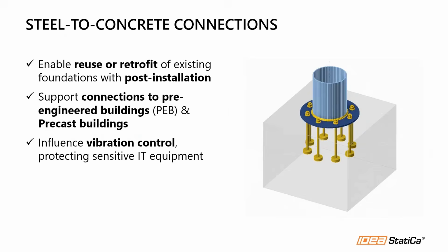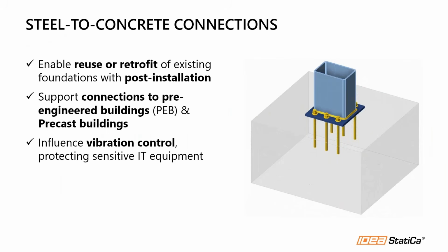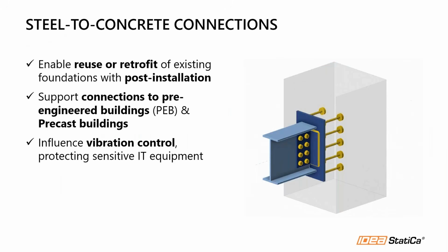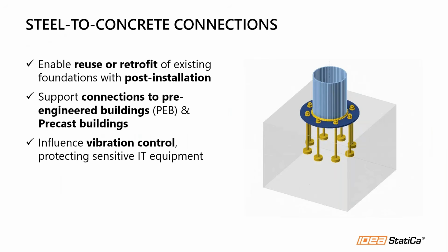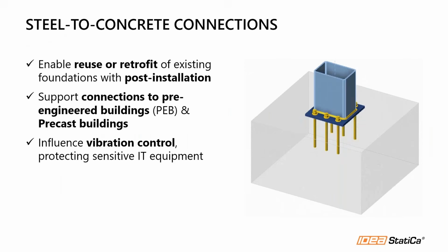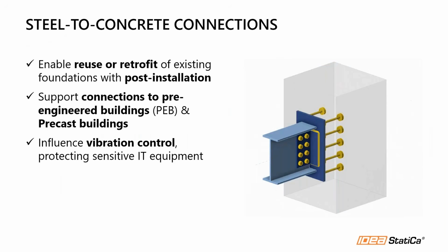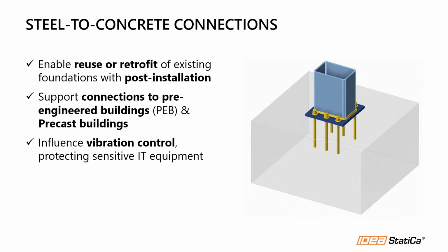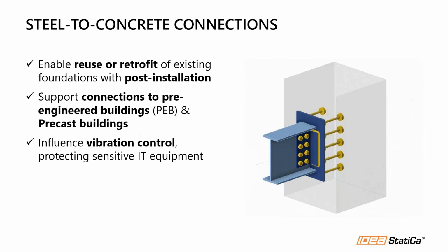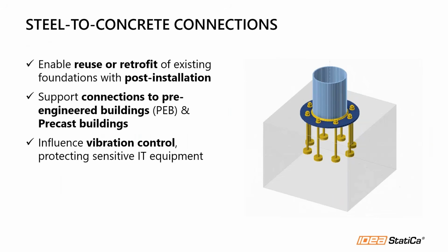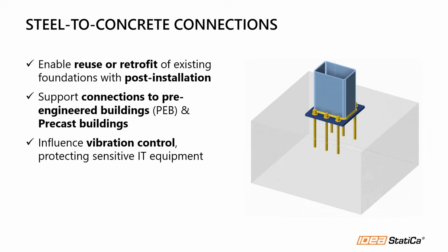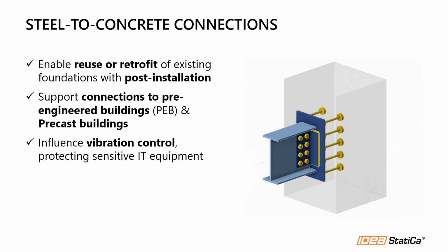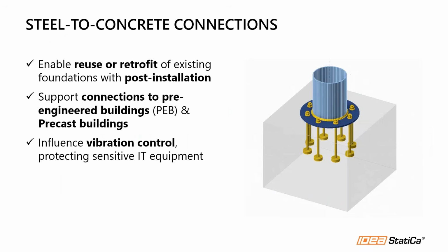Now, one important aspect of data centers is vibration control. Here, connection stiffness and detailing of the base plates directly affect vibration performance, which is very critical for those sensitive IT equipment or server equipment that are housed in the data centers. So being able to model and analyze these connections with their real stiffness and their realistic behavior can greatly benefit the results.